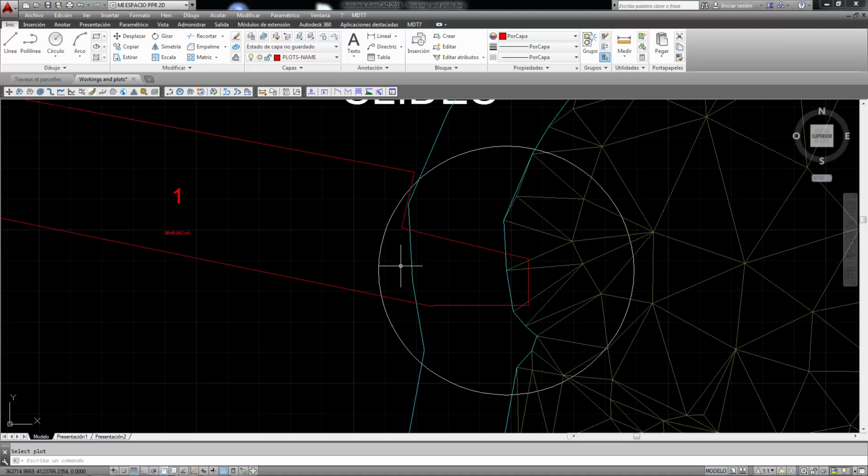We insert the distance at 30 meters. Select the feature and accept. Our 30-meter safety margin enables us to see this section of the plot has been invaded. Let us draw this section of polyline in layer 0 and delete the contour we have placed at an equidistance.